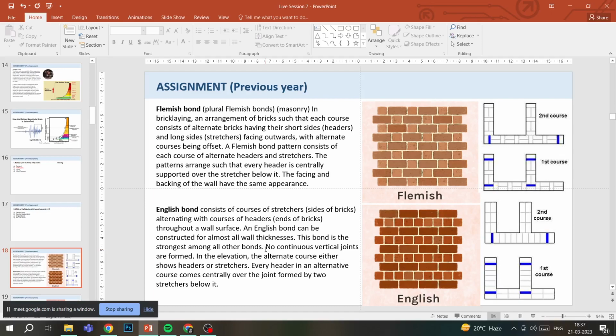Now, if you can see in the image, when the first course is laid, and then the blue mark, what is highlighted in blue here, is actually what I was mentioning, the quoin, Q-U-O-I-N, it is called, and then it is placed to slightly shift the second course so that all the joints don't coincide, otherwise there would be no stability. And this is how it is made.